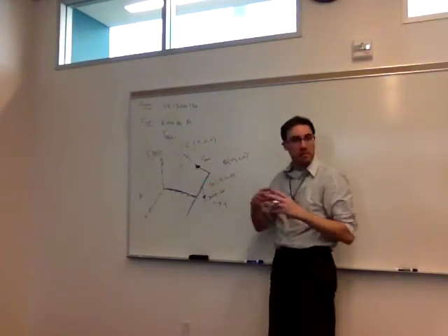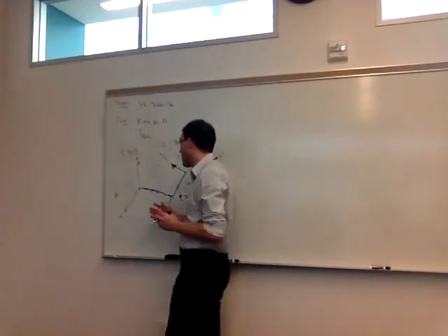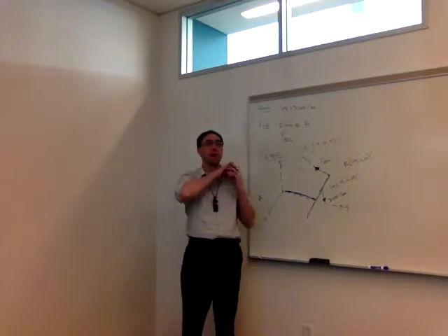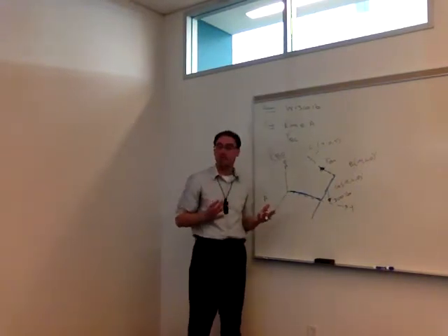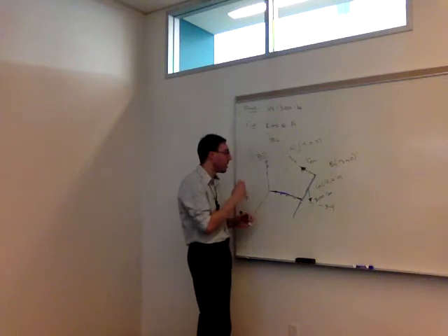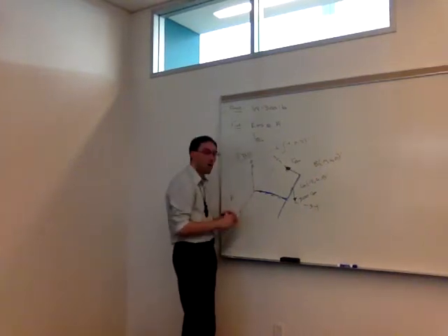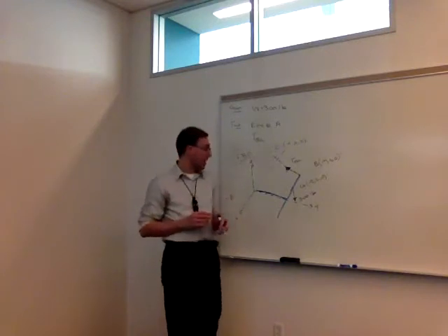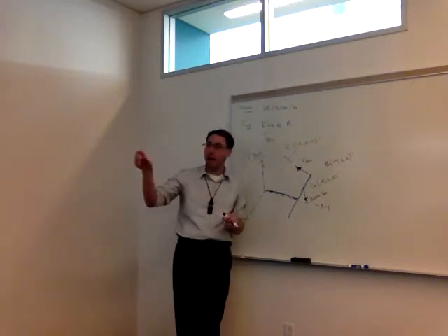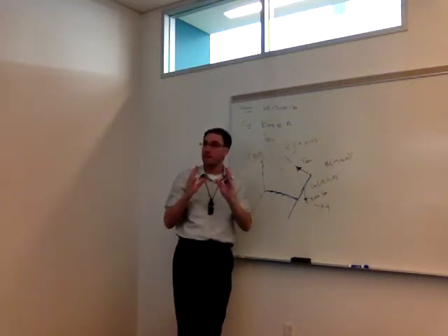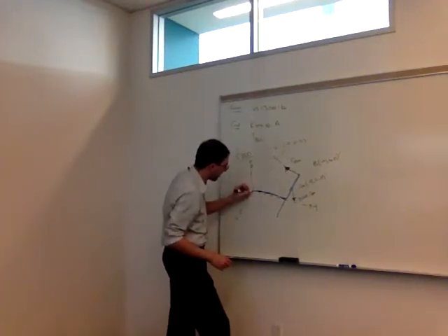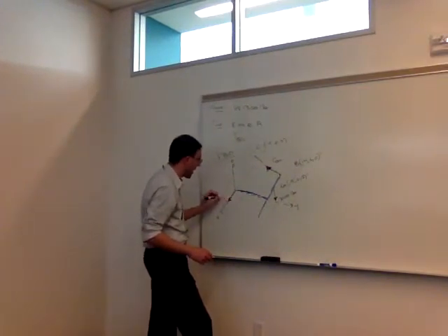All right, so now the hard part is modeling our supports correctly. In this case, we have one support at A. We have the pin connection there. So we can look at that list of how a pin is usually modeled and go off that. Or again, for now, just think about in each translational or rotational direction, can it do it or can it not? So in regards to the x-axis, can we move this T-beam along the x-axis when it's connected to the pin? Right, so the pin, we're going to assume that it is rigidly fixed there, so it can't shift any. So it can't move in the x-axis, so we are going to have a force in the x-axis. I'll assume positive x, and I'll call that A sub x.